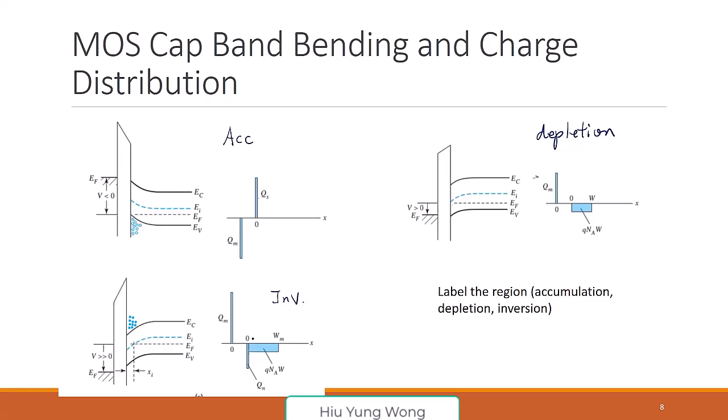The key to this MOSFET is that when we start attracting negative charge for NMOS or positive charge for PMOS, we actually start depleting the carriers. We increase the depletion width, and this does not contribute to current. This is immobile. So you need to wait until the bending is enough to accumulate electrons, which are mobile, for current conduction. This is a very important concept.